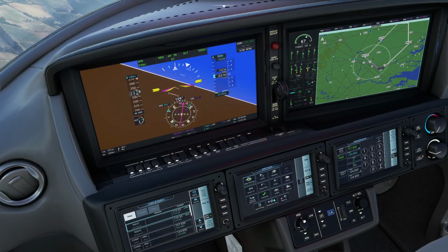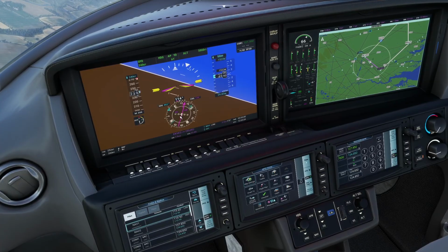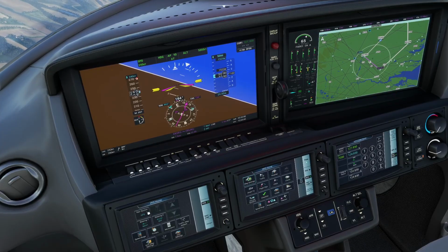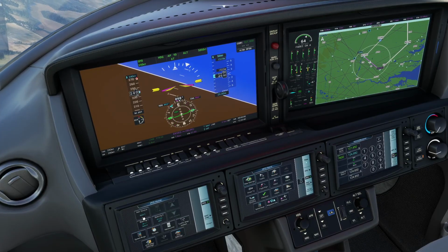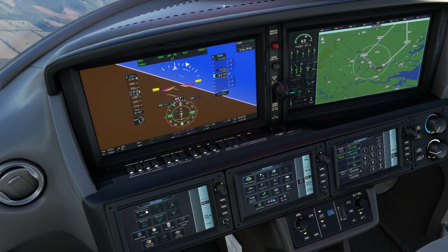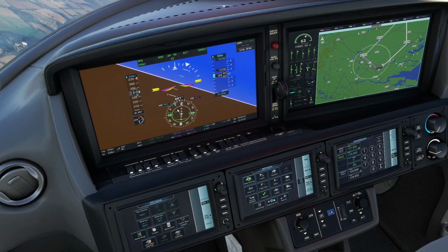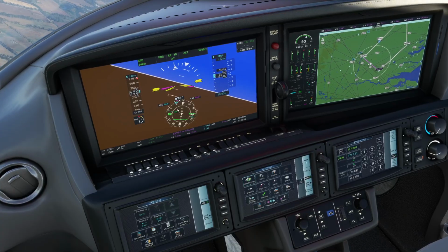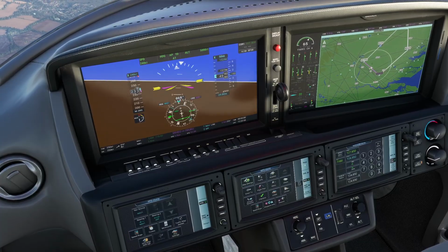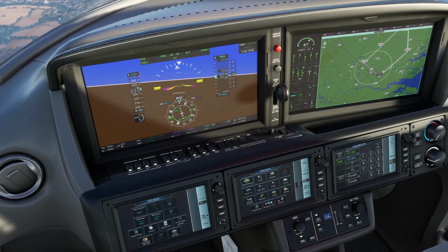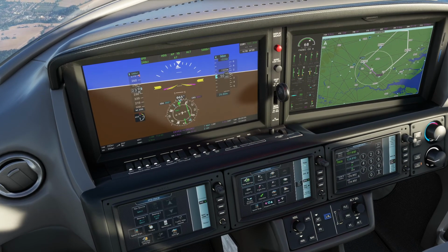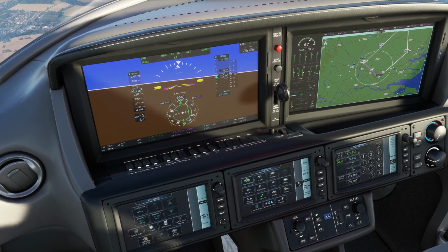So now that's happening, now it's flying on heading mode, we can safely change the mode on the primary flight display of the nav source. So we'll go and change that now to nav 1. So you can see we need to actually change the course though. So the way to do that in the Vision Jet, because there's no button to do it, is hold Control Shift down on the keyboard and use the home and end keys. So we need the course to be 62 degrees. So I'm just spinning the course round to 62 degrees.